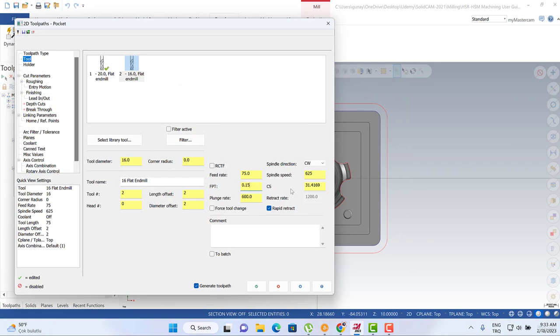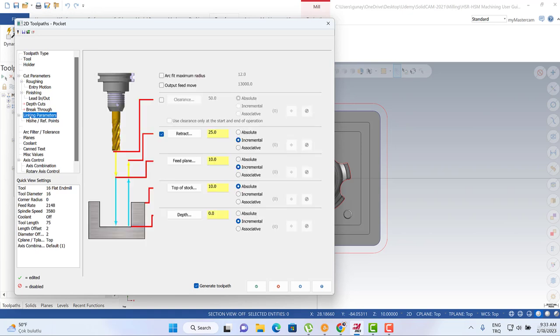and we can organize our feed rate. My feed rate and cutting speed can be like this. After that, let me turn to the linking parameters to organize my Z area. I can hit the absolute coordinate system. It means that we're gonna focus on the MasterCAM VCS, with the retract position absolute 5, and the feed plane absolute 1. This is the last feed rate for use, and the rapid movement G0. After that, we're gonna turn to the G1.